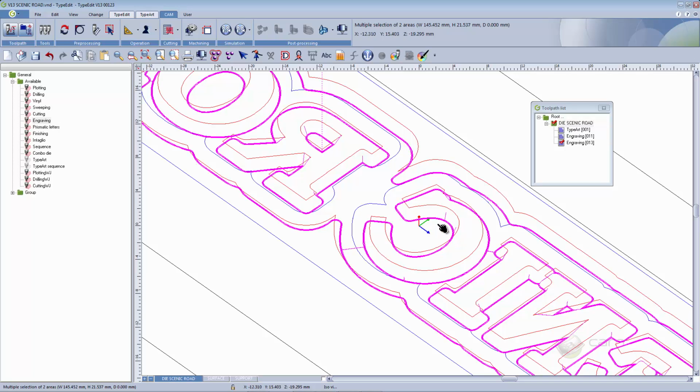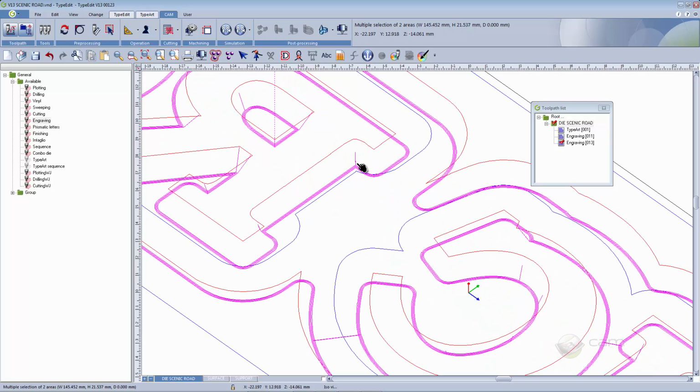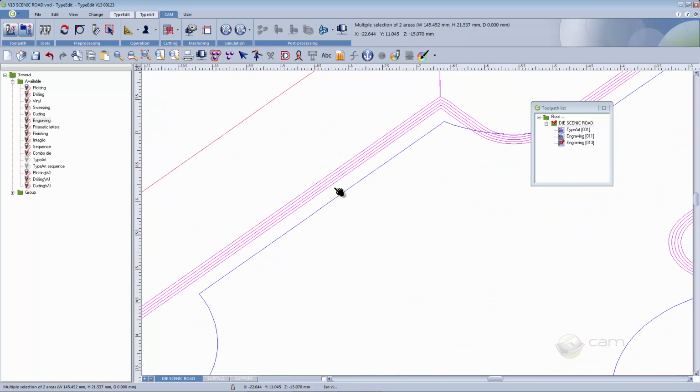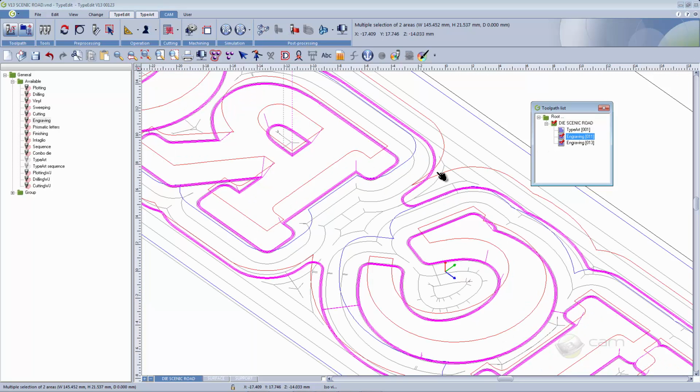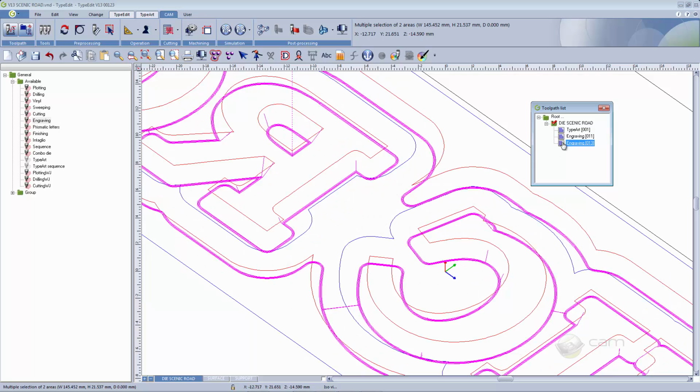So with this view you can see two pieces of information. One, here we are doing 2D half, and here you can see we are doing only 4 lateral slices because in the middle the previous, bigger tool had already removed the material.